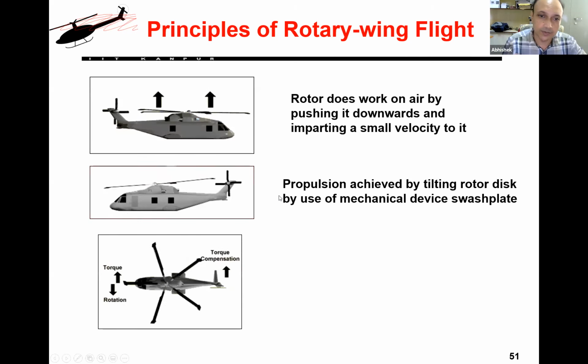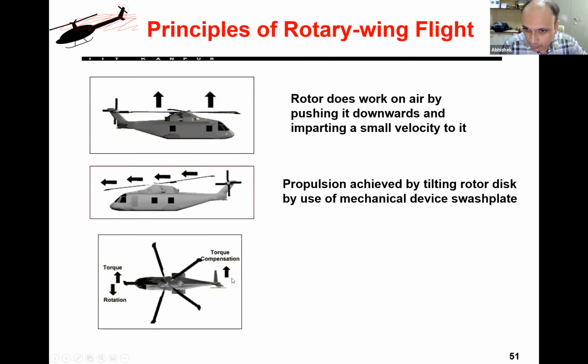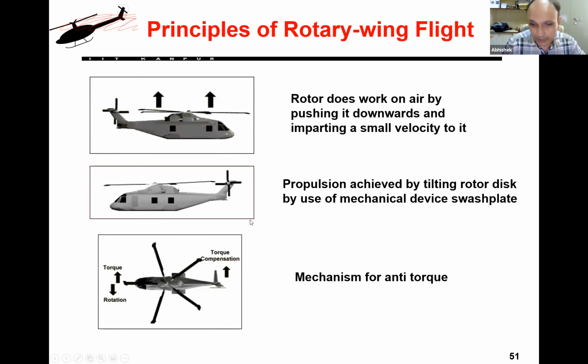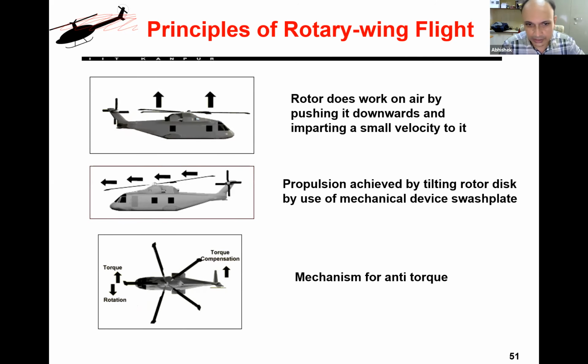And that's why helicopters, or rotating vehicles, are called the true 6 degrees of freedom aerial vehicles. Vehicles which can fly in any dimension, any direction. Now, a conventional helicopter requires a tail rotor for torque compensation, or you require a second rotor. As you saw, there are multi-rotor concepts with other rotors spinning in the counter direction to balance out torque.